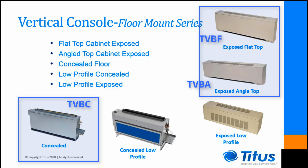The TVBF is a flat-topped unit while the TVBA has an angled top to it. The TVBA is much more suited for school buildings where younger children are located. The angled top prevents books, backpacks, and other educating items from being placed on top of the unit and blocking the supply air opening. These items tend to slide off the top of the unit when placed there.